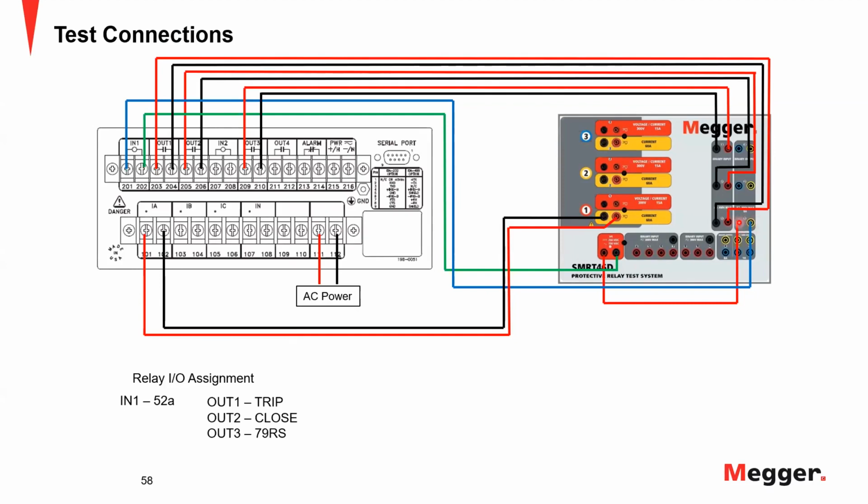It's controllable by the logic, so you want to series the contact, the input to the relay, and the voltage all together. So in this situation, you come out of the positive, into the programmable contact, out of the contact, all the way over to the input, and then from the negative side of the input back to the negative of your battery source.